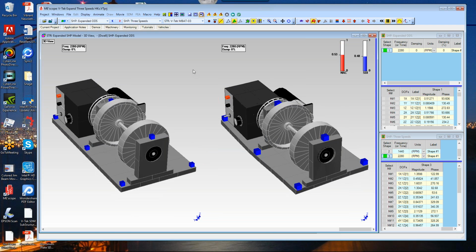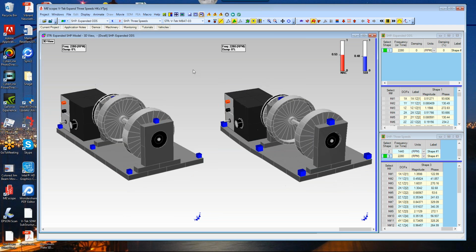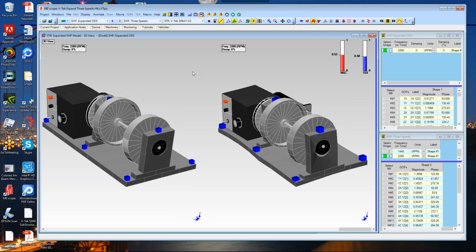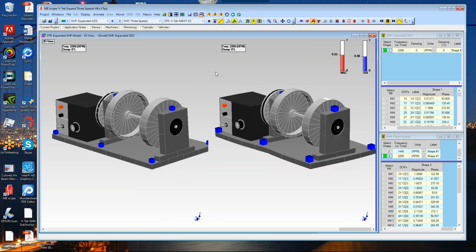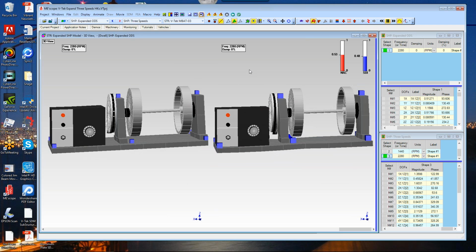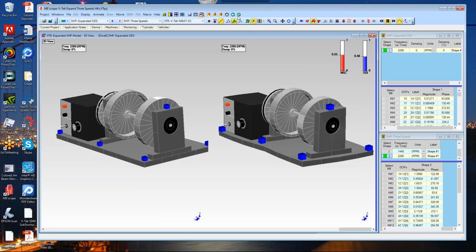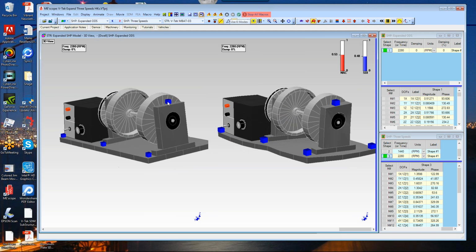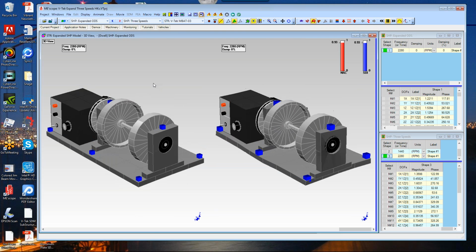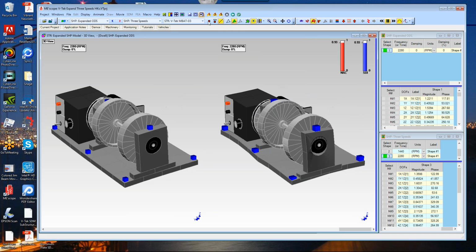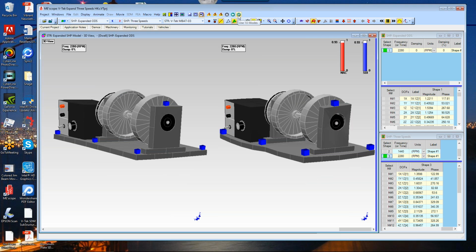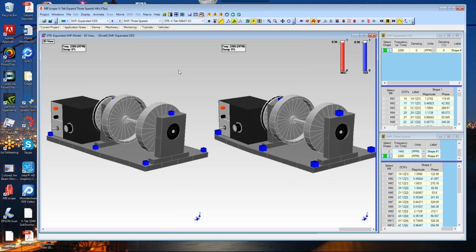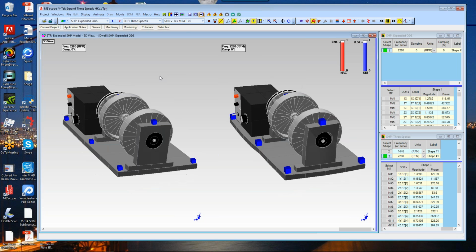Again we're at the high frequency, 2280 RPM, where the machine base starts to flex a little bit, along with the bearing blocks, and I really need at least 6 of the modes from my modal model, and now I've got a 93% match. If I use 10 modes, I get a 94% match of the analytical modal model to the experimental data.